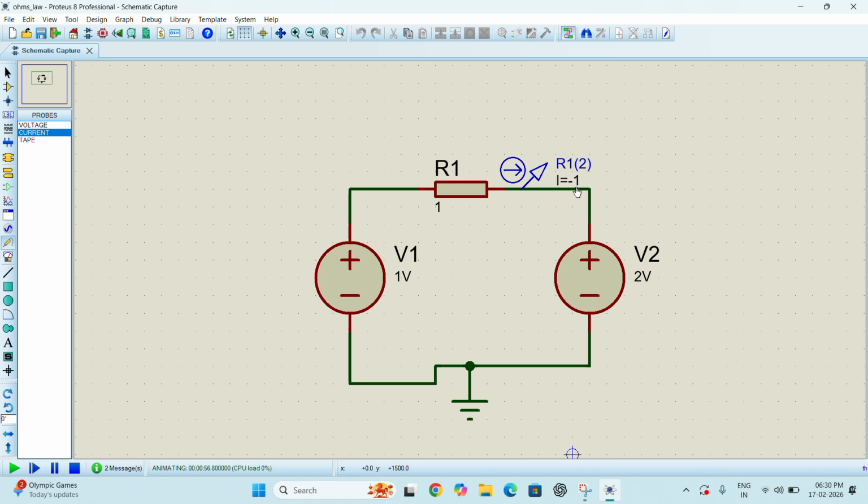I is what? 1. So 1 square into 1. R is 1. So a 1 watt resistor you have to choose while using in this same circuit when you are building it on the breadboard or somewhere. Means you have to choose a resistor such as a 1 ohm resistor with a 1 watt value. There is always a power rating with the resistor.